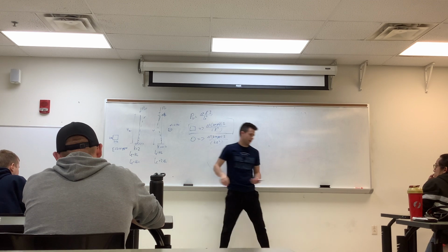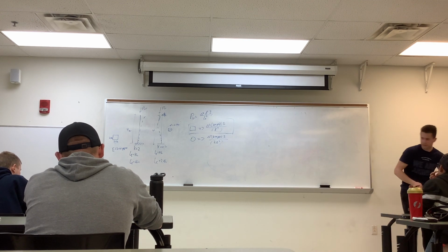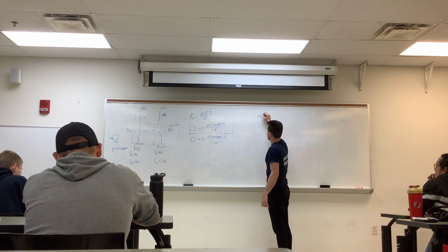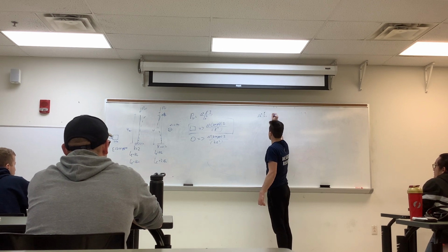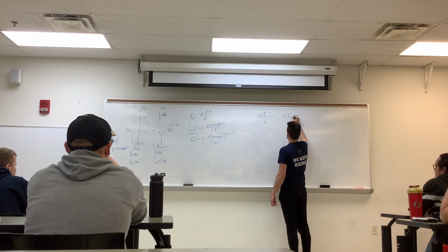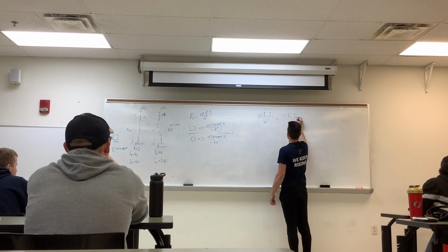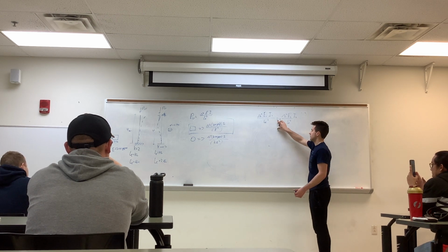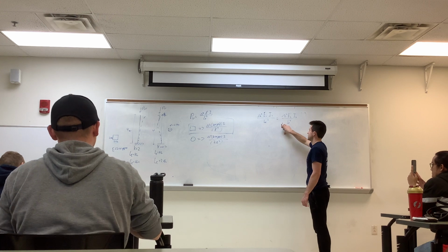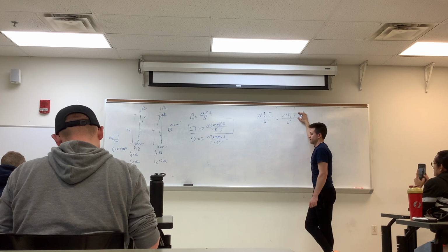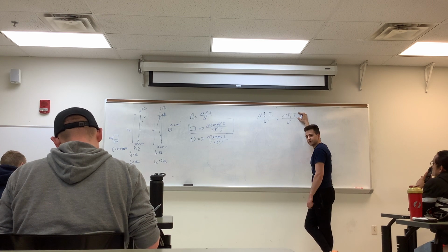And if you remember how we did the one from yesterday, we had two separate columns with two different cross sections, and we had it as pi squared E1 I1 over length effective squared is equal to pi squared E2 I2 over, again, the length effective squared. So even if you have almost all of these values, if I don't give you the modulus of elasticity or moment of inertia of one of them, you can solve for it using the other column if the critical buckling load is the same.